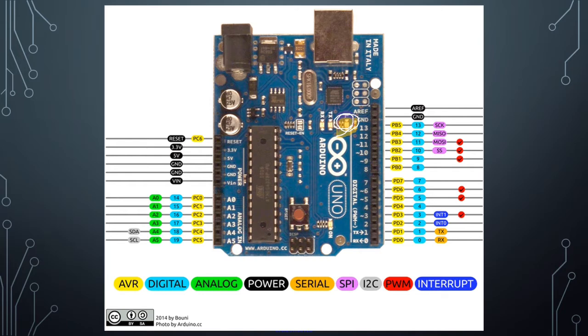It's an integrated LED is what it's called, and it's tied to pin 13. So if we reference pin 13 in our code, this LED on the board will also take the same action. So if we tell whatever's connected to pin 13 to blink, the integrated LED will blink too. And so we'll be using this in the first part of our lab.